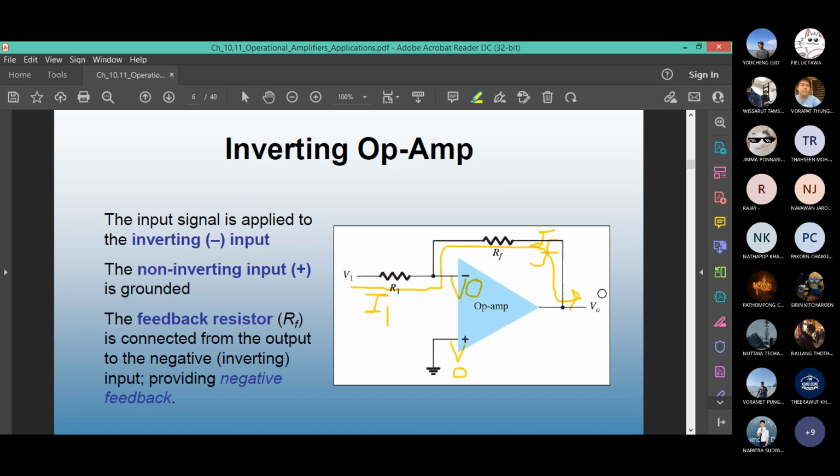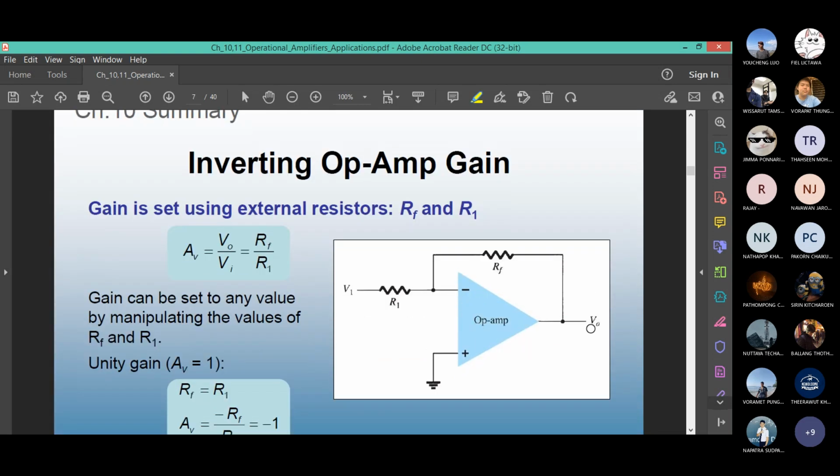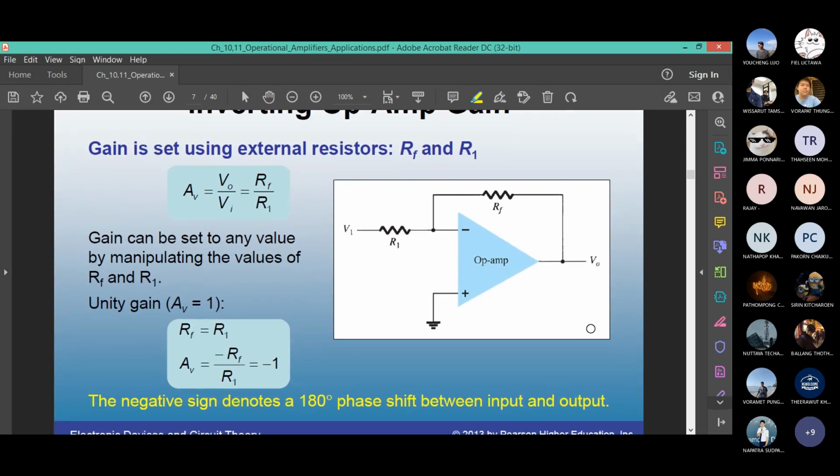It's a minus sign. Whatever you put inside is multiplied by the gain and the sign is flipped. This is for inverting. It provides a negative feedback from the output back to the input. The gain is less than the open loop gain, but it stabilizes the operation. So this is what I told you.